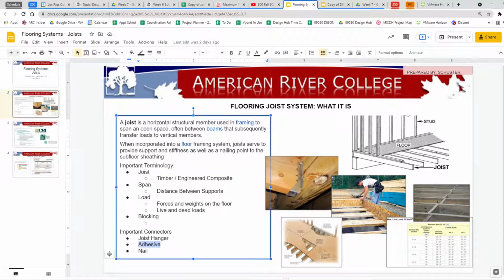Sometimes there's a lot of adhesive involved. The adhesive is often on the flooring side, where along the top of the joist, you'll run adhesive as well as nail it. That's fairly commonly done, that you get adhesive in here with these. And of course, nailing and nail guns, bang, bang, bang, bang. Nail guns are very fast. They're not as